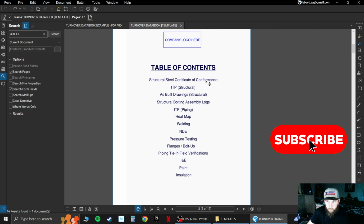Got a certificate of conformance for your structural steel, ITPs, your as-built drawings, which would be basically, for me, my walk downs that show my highlights and what's accepted. My bolting logs, which is basically a checklist for when I'm walking down steel. You have your piping ITPs, your heat map, your welding section, your NDE section, pressure testing, your flanges, your bolt up mapping and all the verifications.